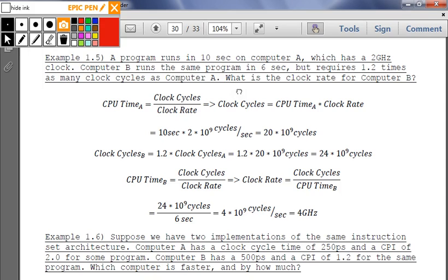Okay, so just go a little bit. This is slightly outside the scope of the course, but the idea is you want to be able to maintain the integrity of the signal. Sometimes you have to use buffers at those interconnect stages to restore the signal, because it begins to degrade a little bit. And it's harder and harder to keep the integrity of the signal the faster the clock rate goes, because you have to get from 0 to 1. We're in advanced digital systems, so this is actually a very relevant question.